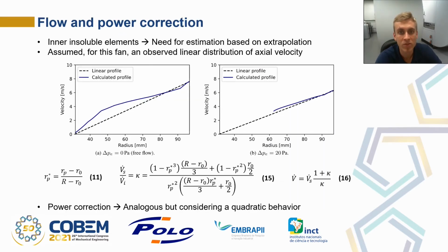In the inner elements of the model, a phenomenon of insolvence takes place, where no mathematical solution for the nonlinear system can be found. It occurs because with the reduction of the radius there is a reduction of the chord length. To compensate for that, a larger lift coefficient is required to maintain the thrust, which in turn demands a higher angle of attack until the stall point is reached.